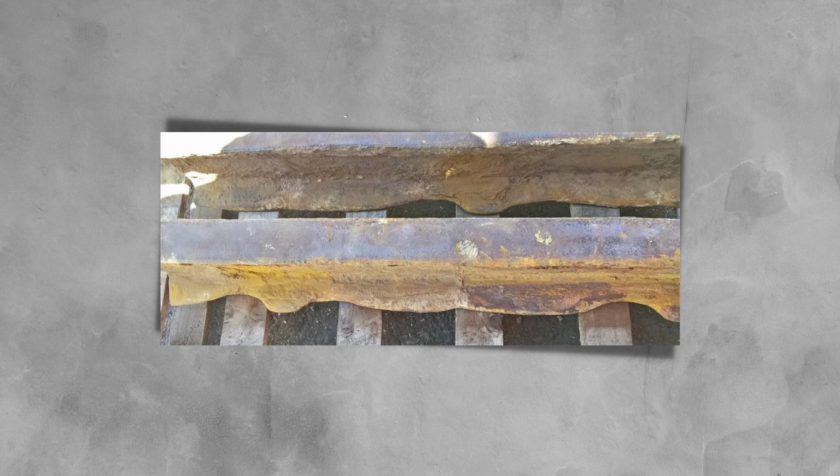The foot of the rail is particularly susceptible to corrosion as it often sits in areas that are wet, dirty with contaminants such as road salt and grit, like tunnels, under overbridges or in level crossings. These areas speed up the rate of corrosion compared to open areas where water drains away. Level crossings are a particular area of risk due to road gritting and salting in the winter months. Because of this, the level crossing decks are lifted to allow the rail foot to be inspected. On main road level crossings, rails with special coatings can be installed to help increase resistance to corrosion.